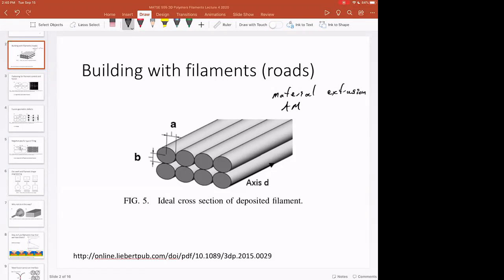And this is different than if you make polymer parts out of injection molding, where you just injection mold or mold a cavity. You get a solid part out of that. Depending on how the part is designed, you might have to glue two pieces together or something like that if you can't injection mold the part all as one piece. But injection molding, even though you do polymer extrusion, you don't wind up with these roads. But when you watch a video on YouTube about MakerBot printing, or you watch that Ultimaker printing video that we covered when we were talking about the support, the entire part is made up of these filaments or strings of extruded polymer. We're going to call them roads because that's their scientific name.